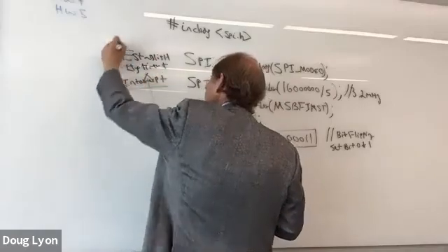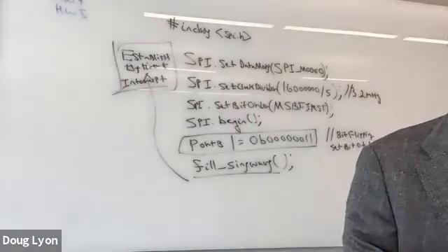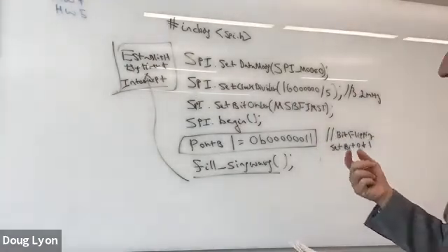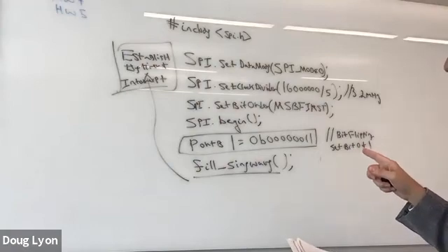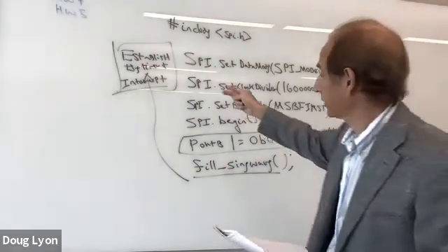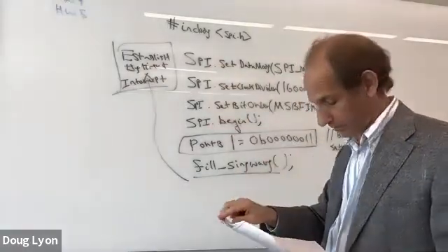The goal here is to use the interrupt in order to be able to tell the Arduino when to get another sample and put it into the data port, that is to put it into the SPI. Meanwhile, in between interrupts, it can do other things.